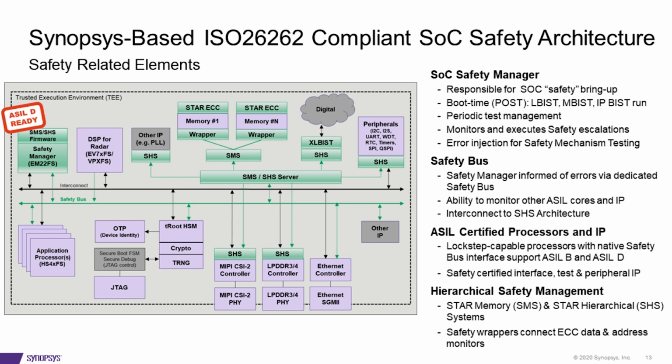So how does that look when you bring that into an entire SoC? You can see there on the far left, and this is just an example device, say an ADAS device, with obviously the Synopsys spin on the peripherals and the processors there. But typically, regardless of whether it's a Synopsys-based IC or not, you see this common architecture where the safety manager and all the safety-related elements are highlighted in green.